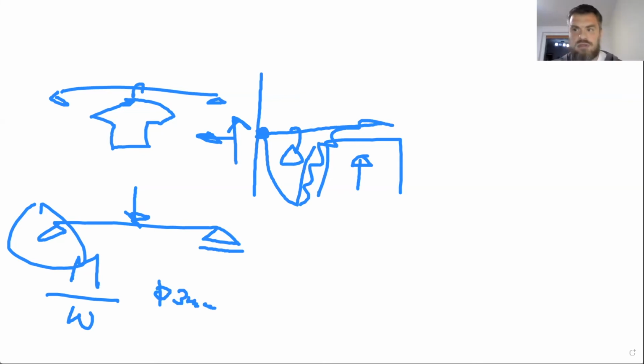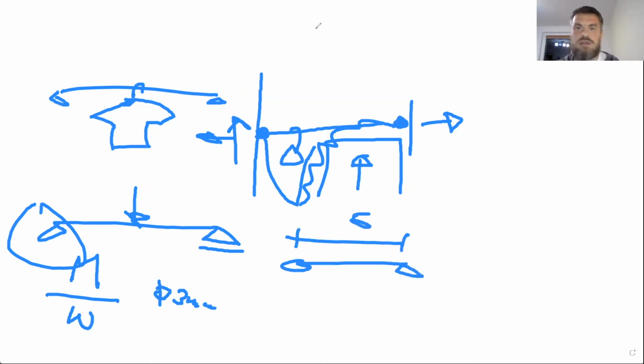Why? Because this is not how it works, on a very simple principle. For the laundry string to work, you have to have 2 supports that can transfer horizontal directions. This is why you use relatively good bolts to attach a laundry string to the wall, because you are afraid that they will be pulled off the wall by the weight of the laundry. Why? Because when you have 2 supports 5 meters away, the string that deforms actually gets longer than 5 meters.